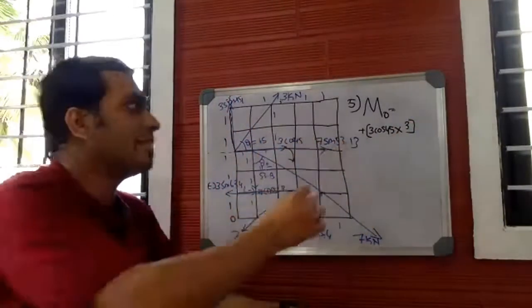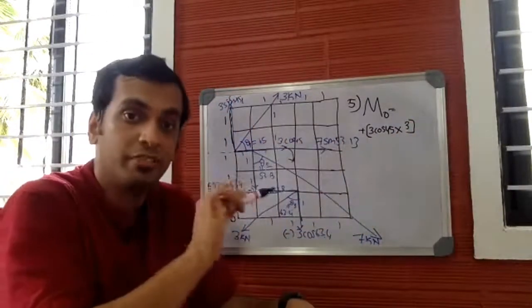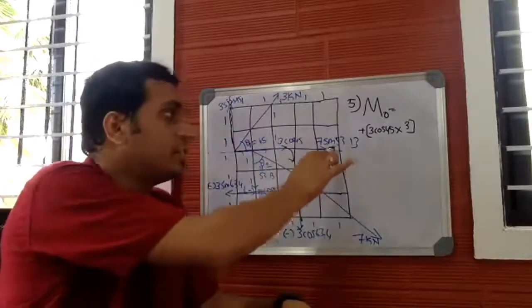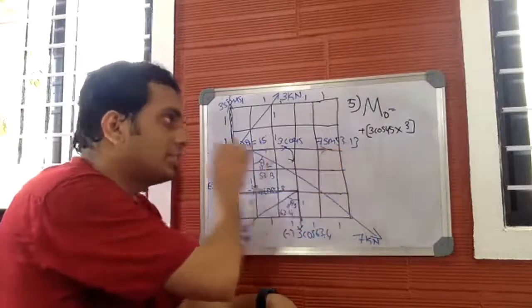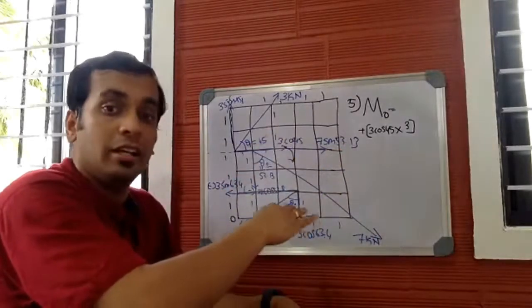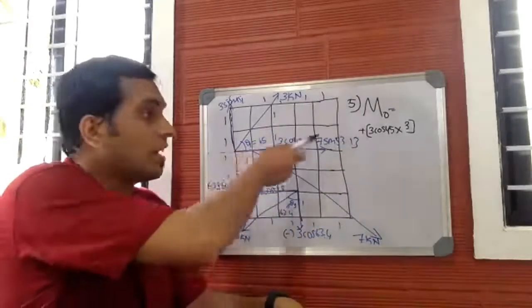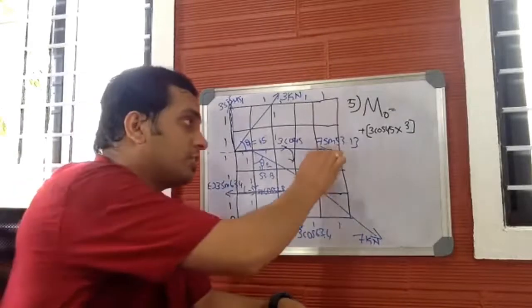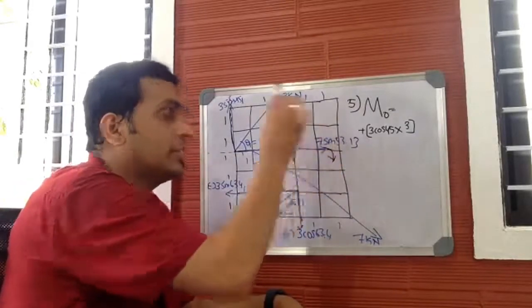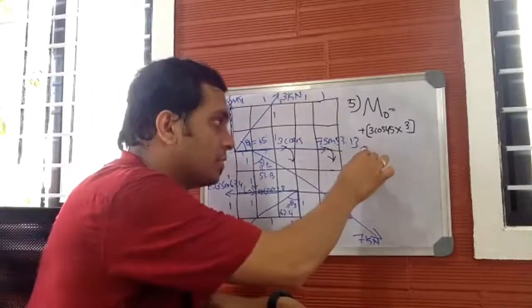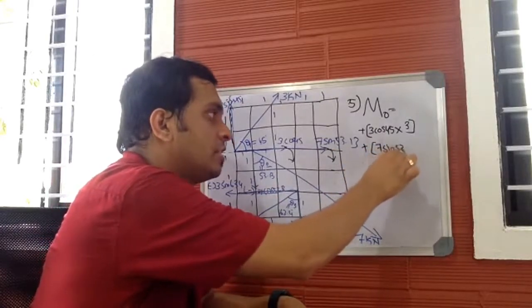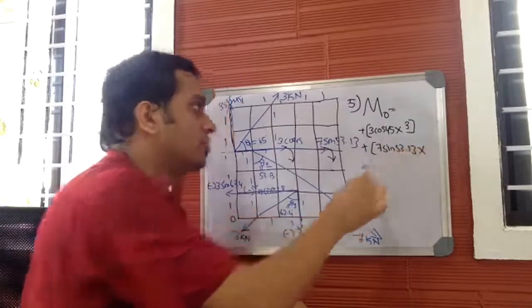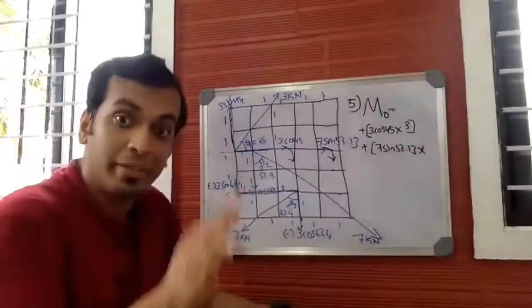Let us concentrate on 7 sin 53.13. Check whether 7 sin 53.13 produces clockwise or anti-clockwise moment about the point O. Even this is horizontal, the point lies below the line of action of the force, and the force acts horizontal to the right-hand side. So this force should produce moment in the clockwise direction. So again it is plus 7 sin 53.13 into, what's the perpendicular distance? Again the perpendicular distance remains the same, it is 3.